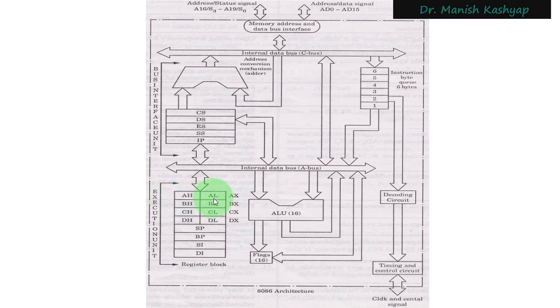Now, like in the case of 8085 microprocessor, we called A register the accumulator. So here also AX register is called the accumulator register. Now, like in 8085, A register was responsible for default calculations, and it was also present in some default commands. The same will apply here also, but the involvement of this particular register in default calculation is less as compared to 8085.